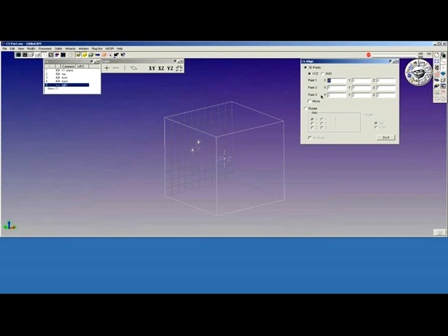The choice that I select to move this CS is going to be rotate. Now the rotate option takes an existing CS and rotates it around an axis to a specific angular location. Now, if I want to rotate this coordinate system to the right side of my cube, I first determine the axis of rotation. I'm going to rotate around the vertical axis.